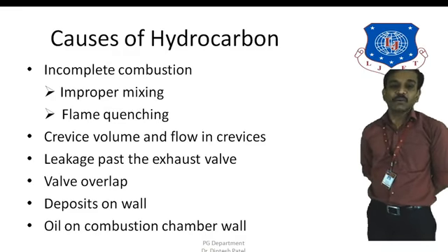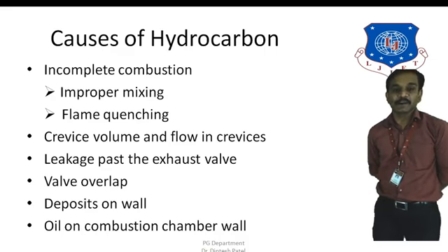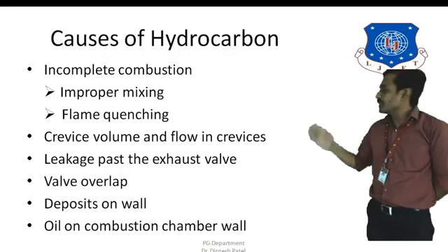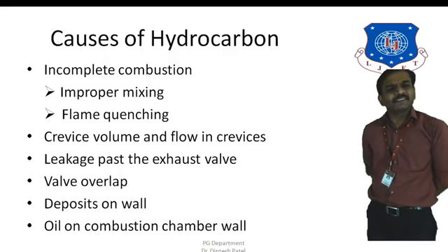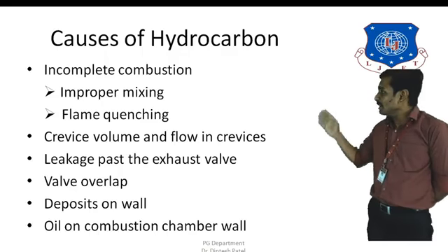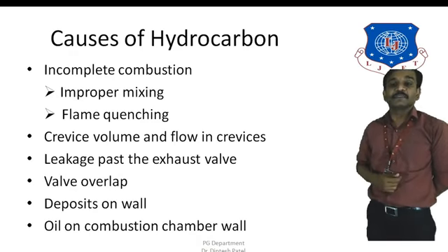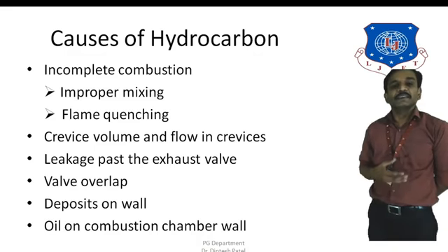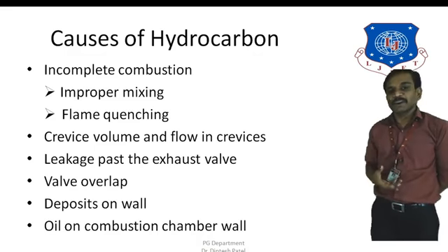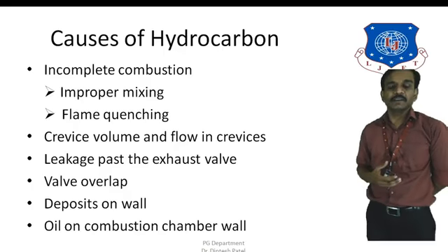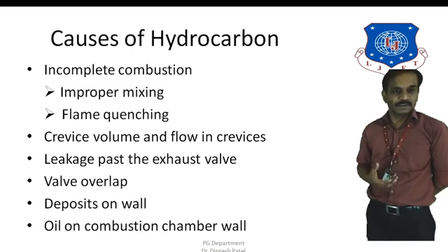This is a major cause of the creation of hydrocarbons inside the combustion chamber, and there are a couple more things that describe the types or conditions of incomplete combustion. Even perfect combustion is mostly not achieved in the combustion chamber. However, even if the combustion is nearly perfect, a certain amount of hydrocarbon is always produced.